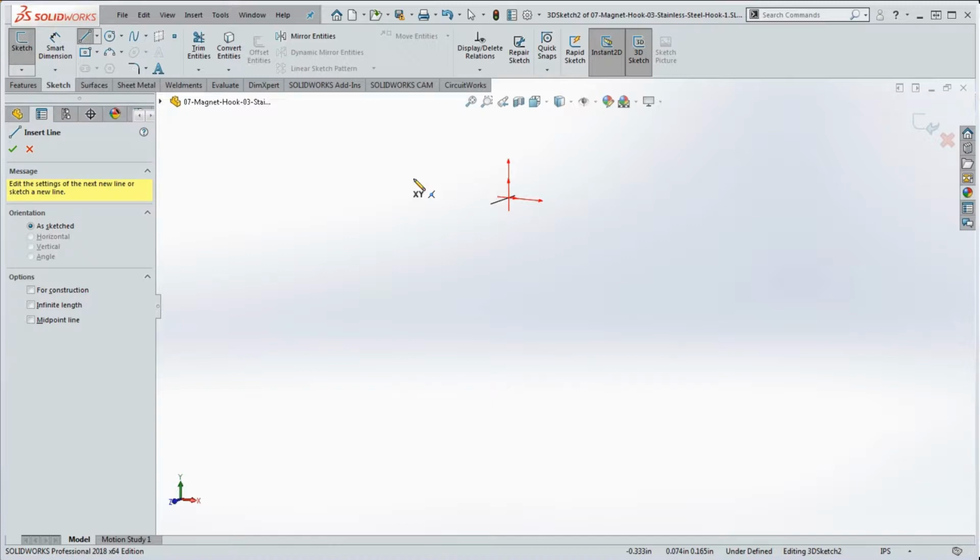But it's also telling us that we're going to be sketching along the X, Y plane in a way. So if you think about that, it's parallel to the front plane. As we sketch this out, it's going to be on a plane that's parallel to the XY plane as defined by the triad down here. Now we could take our tab key and try this. Take the tab key and tab it. And you'll notice that the orientation now changes too. Now it's YZ. Press it again, it's going to be ZX. And press it a third time, we go back to where we were before.